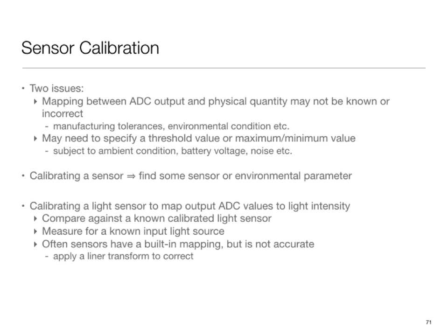Chemical sensors usually come in the form of giving you a fluid of known value, and then you test against it. For example, some of the medical things like those diabetes strips come with a reference strip with which the meter is supposed to be recalibrated once in a while. So sensor calibration, and doing it in the field at runtime, is important.